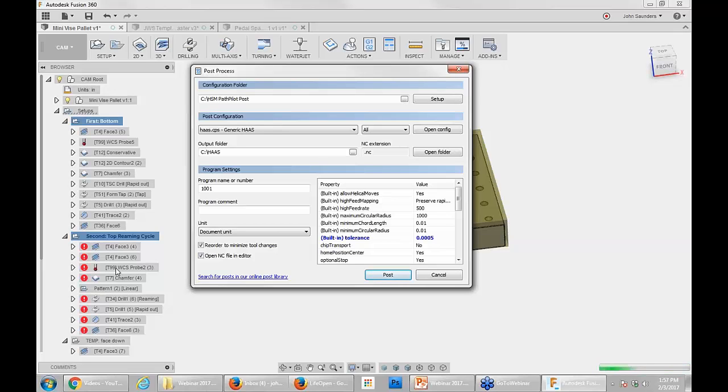Okay, so a couple more questions on this. We're quickly running out of time, and I apologize, but we've got a weekly hangout, so you guys can always come back again next week too. So the question Seth is asking, does it ignore multiple uses of the tool? So really what this minimized tool changes is what we call a traveling salesman algorithm. I'm done at this shop, but I've already got all these parts in my car. What's the next shop that needs these parts? So I'm going to use the half-inch tool for all the cases that's needed on this setup. But before going to get a new tool for this setup, it's saying, one of my other setups needs the tool that I already have as its next tool. And if that's the case, it's going to go and do that. Hopefully that helps understand what's going on.